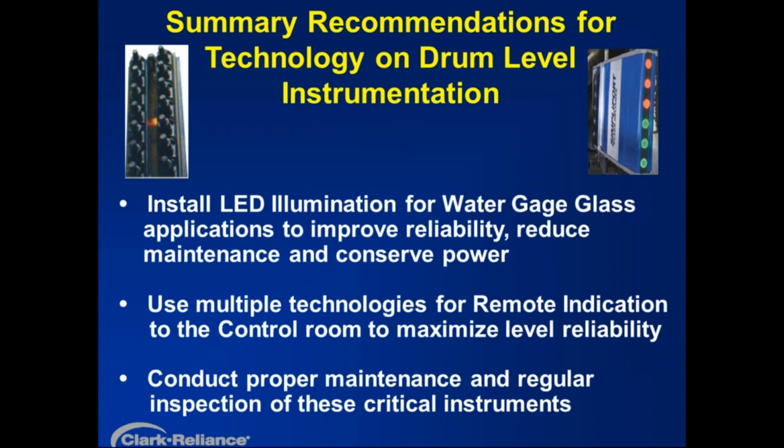When you're applying remote level indicators onto your boiler, using multiple technologies will guard you from a single component or single design failure taking both of your level instruments down. Very likely, if you have the same technology on your boiler, two of the same, and they were both manufactured at the same time, if there ever is any kind of issue, that could affect or compromise your reliability. But if you have, say, a conductivity probe device and a DP transmitter, or a conductivity probe device and a guided wave, you've got two technologies operating on different principles, and your reliability is that much better.